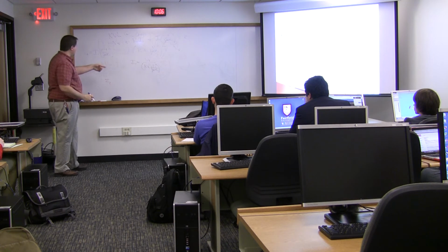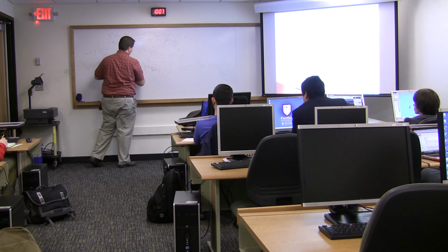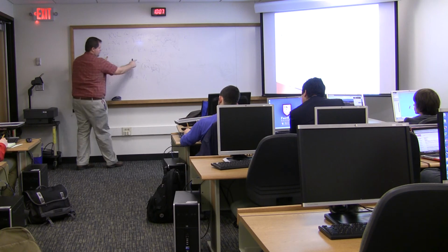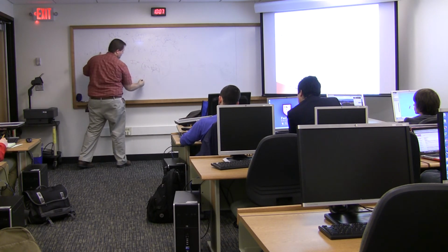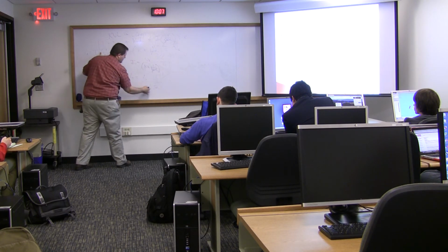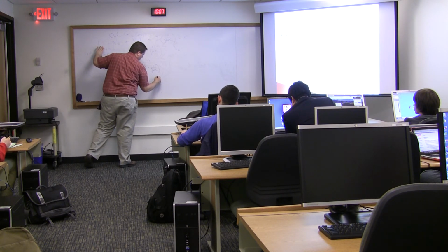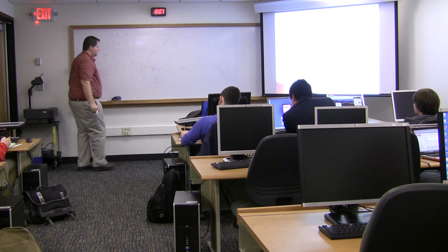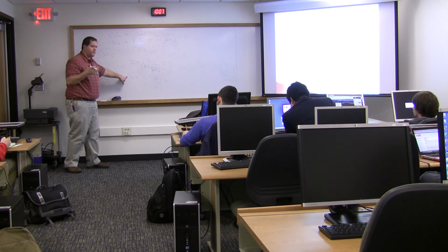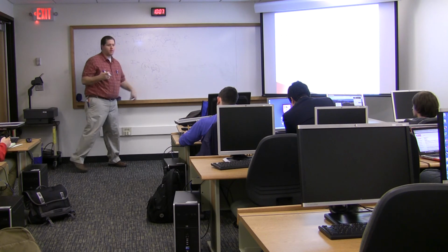Okay. So I have I, but I really want Vout, right? So I need to take I times this 1 over j omega C. So Vout equals Vs over R plus 1 over j omega C, times 1 over j omega C. I now have the output voltage in terms of my input voltage times something.